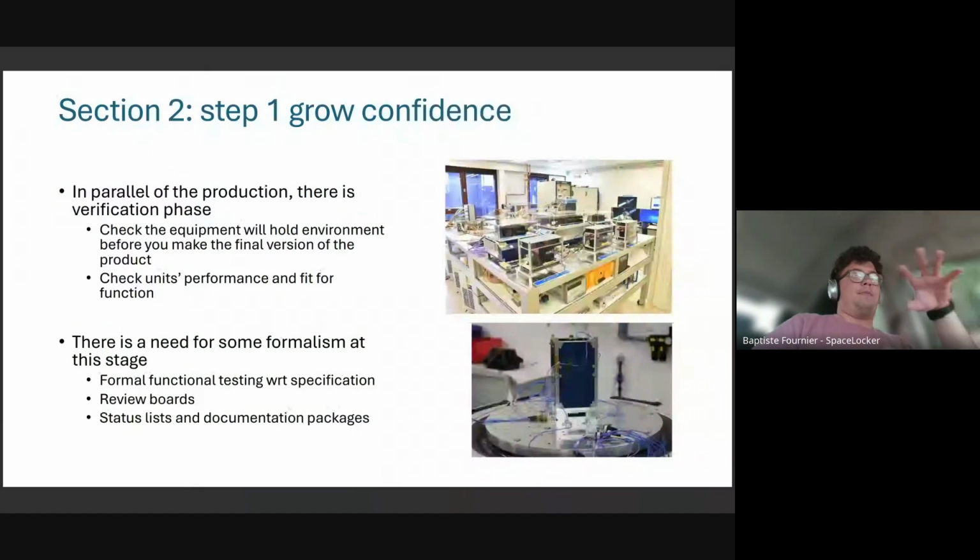So I started on the top left, top right, bottom left, and then bottom right, which is the environmental testing. This is not qualification. What you're seeing is a structural model of a first mission. A structural model gives you confidence in your digital modeling. You sort of tune your digital modeling, your finite elements analysis, your computer model of your payload that will give you a lot of answers.